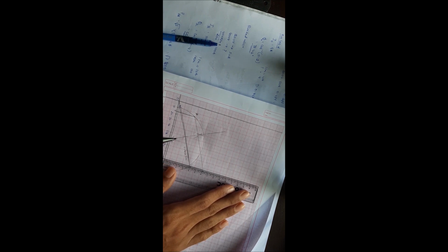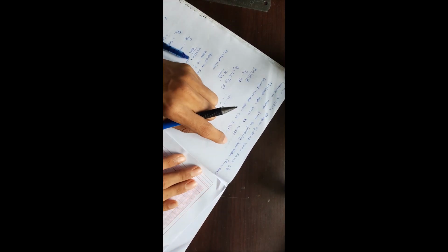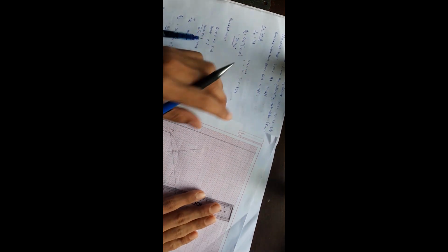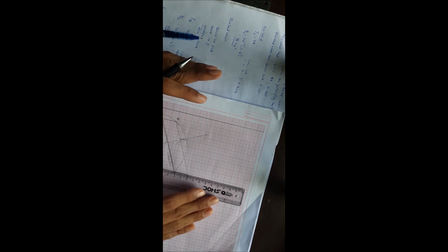That is our copper loss of stator and rotor. Here we have to check whether any condition is given, like percentage of copper loss 50%, 60%. Here it is not given. So we have to take stator copper loss equal to rotor copper loss, means it will be 50-50.